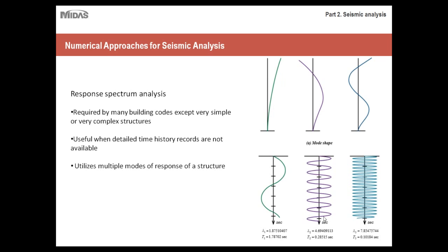Whereas when the earthquake increases in frequency and strength, you'd have a second mode shape that you'd run calculations for, and you'd assume that the forces would act in such a way. For example, you might have a node here, with a force acting this way, and then a node here, with a force acting this way. Whereas in the first mode, you'd only have one force acting this way. And then finally, maybe you'd have a third mode for critical conditions when the earthquake is at its strongest, with maybe three nodes this time, and forces acting this way and this way.